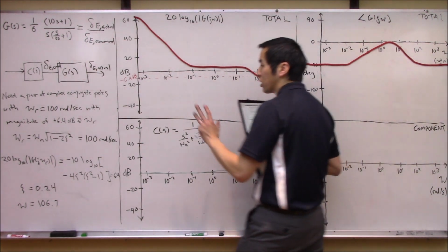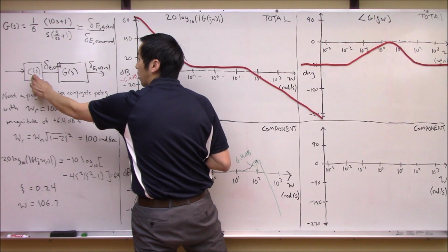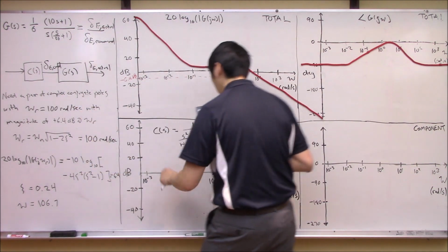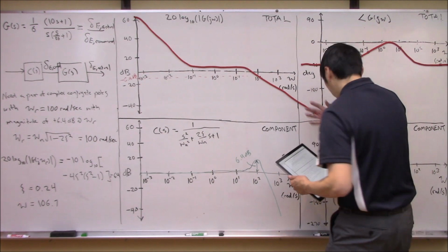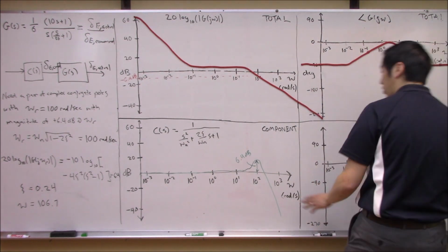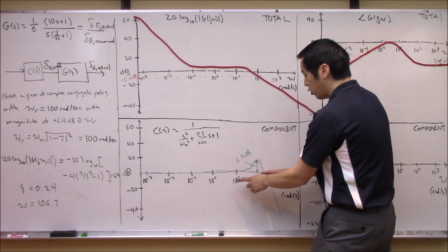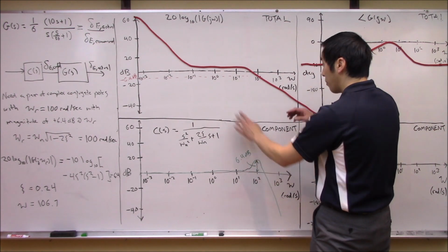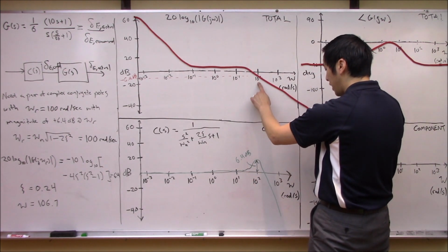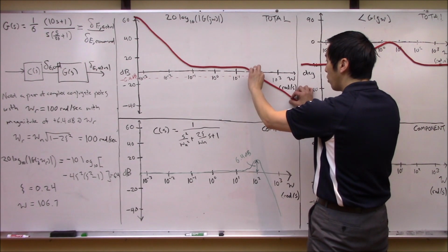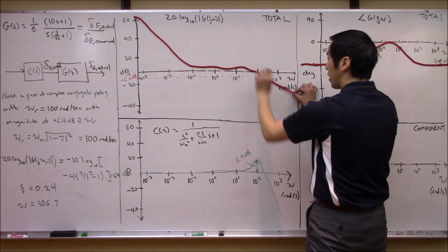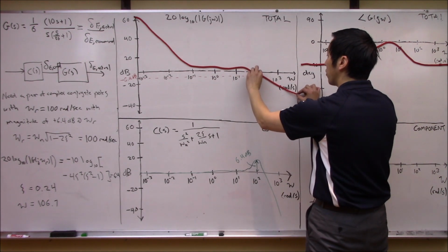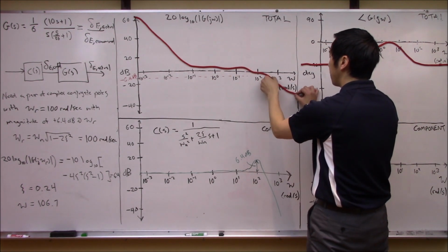So you can think about just, if you just build this little electronic component and you add it right beforehand, it will add this type of a frequency response to the system here. And what is the magnitude going to look like? So now we better go ahead and do this. So what it should do here is basically stay unchanged until you get here, and it will add this bump. So it will bring this part of the Bode plot up to around 0. Oh, sorry, so something like that, right?